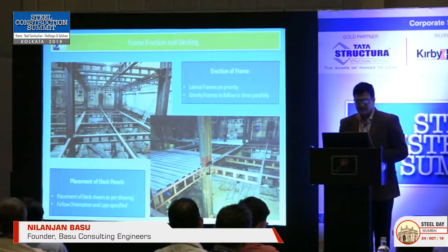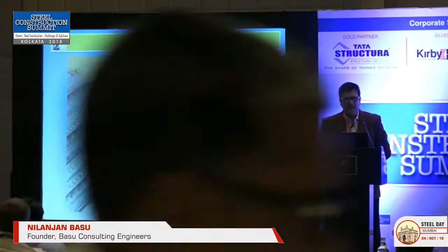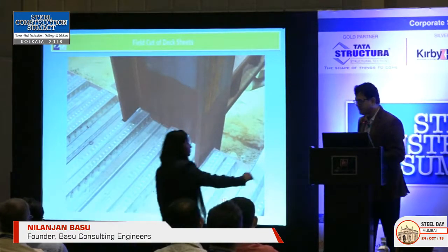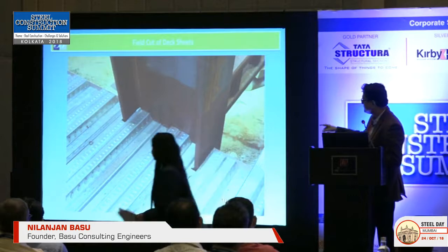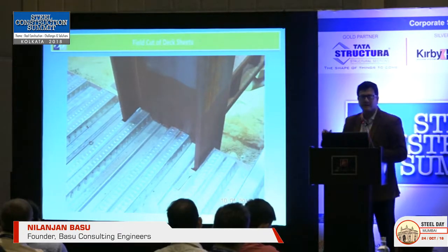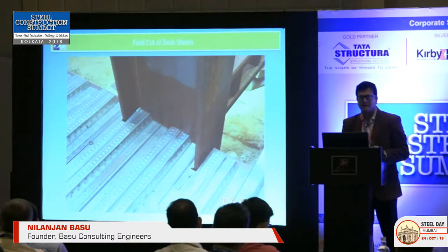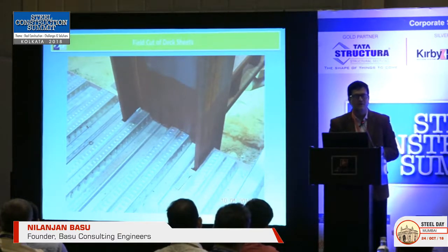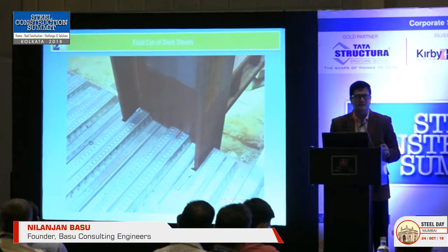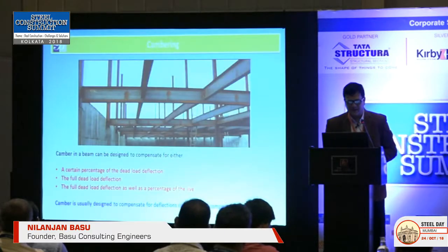Once the layout is done, then comes the cutting part. This is what I was just telling you. Once we have this deck system, we have to make sure that the cutting and the trimming of the decks are done very, very effectively, because you can't weld back the deck. So this is very important during construction, and there has to be proper supervision during that.